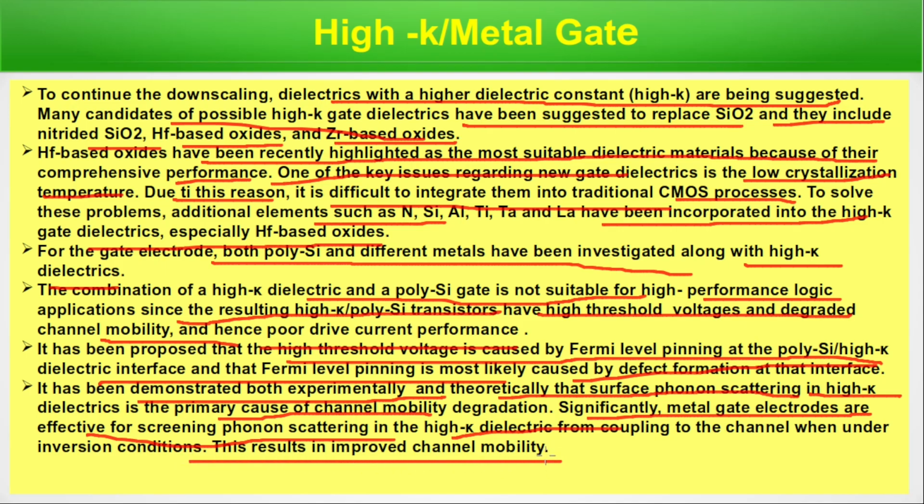Polysilicon high-K dielectric interface, it's not really good for performance. If we replace polysilicon with metal, it gives better results. So we have moved to that high-K dielectric metal combination.